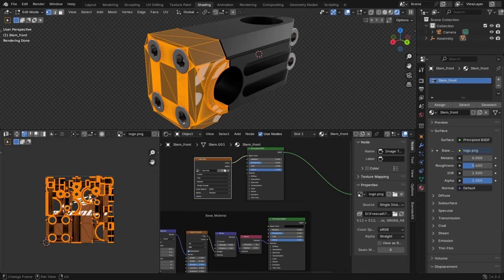I ask you to be very attentive in this part, because it is a bit tricky. It is not the time to go butterfly hunting. All the points and lines of the UVs are orange. This means that they are all selected. If you want to move the UVs, you must use the shortcut G. By pressing G, you will have the possibility to change the position of the UVs.